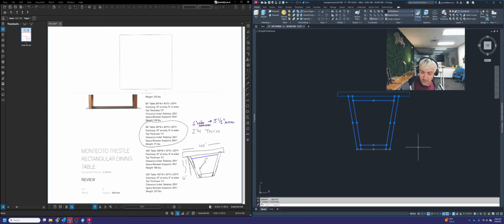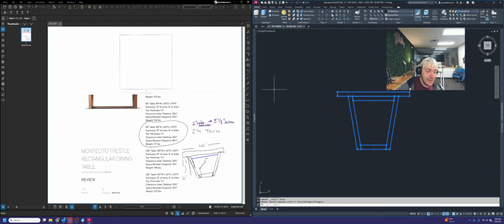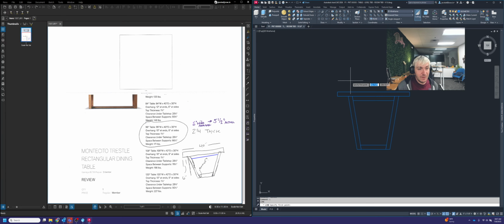Once you have that, you can hit delete, and you should only be left with polylines now. So to check, you highlight everything there, go into properties, and at the top, it's going to say polylines quantity 6. If there's anything else in there, I'll show you what'll happen.